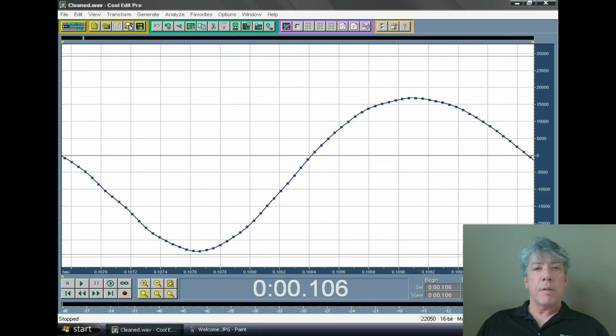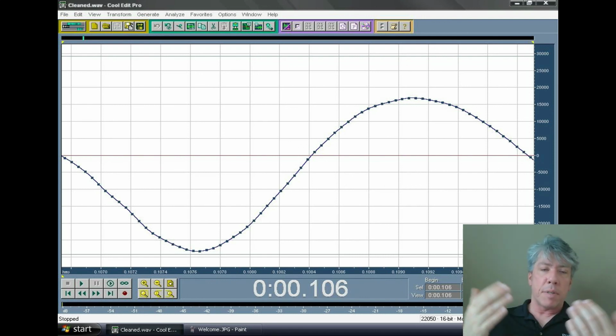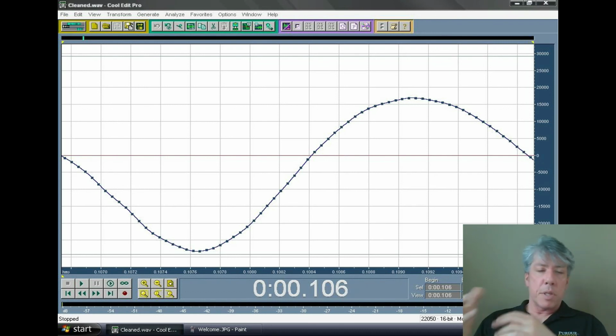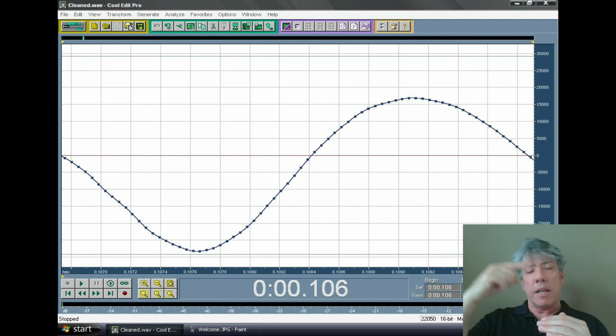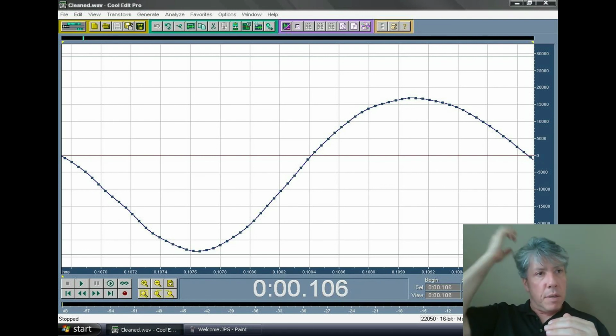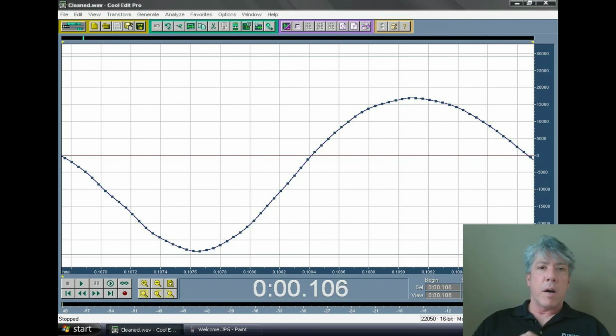Now as far as sampling frequency goes, that's a little more complicated with a PLC, because it depends on whether or not you've got a special input that's tracking it for you, that's automatically doing it, or if it's relying on getting to that point in your code where it goes out and measures it. Really, it has to do with the PLC scan time. So the PLC program, a ladder logic, is scanned, and it takes a certain amount of time to scan it. And then, of course, there's reading inputs, setting outputs, and doing overhead. All of that time it takes gives you an idea of the frequency of how often the sensor is looked at or sampled.